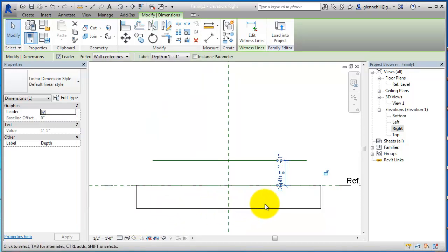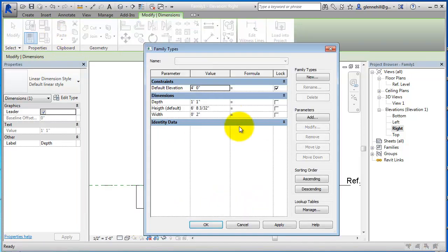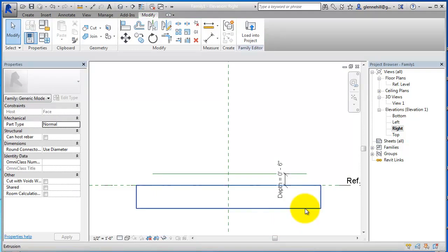So I'm going to change that, and then I'm going to flex it by saying, let's just say this is a 2x6 material. We'll change the height to 6 feet and the depth to 6 inches. So it's 2x6, but not wood, because wood isn't nominally different. Okay, so now we've got my reference lines and they're all flexing correctly.